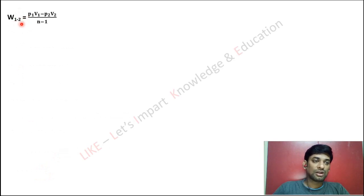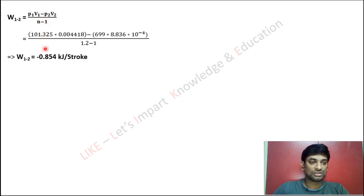You know the formula work done, (P1 V1 minus P2 V2) divided by (n minus 1). Now you have calculated P2 also. So if you substitute all the values, you will be getting work done is equal to minus 0.854 kilojoule per stroke. Listen carefully. Since it is a compression process, the value should be in minus. If it is in plus answer, you have committed mistake somewhere. So you have to see the minus symbol.